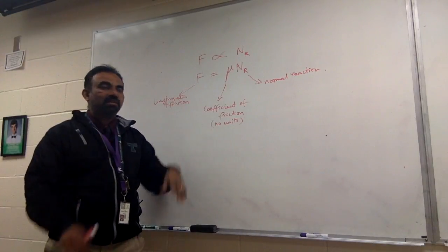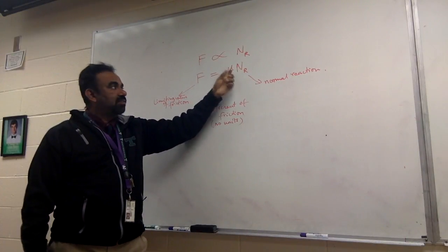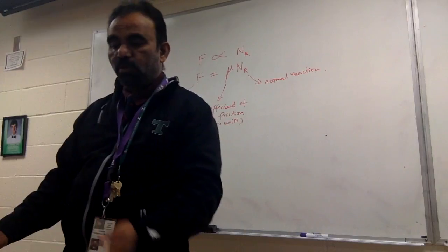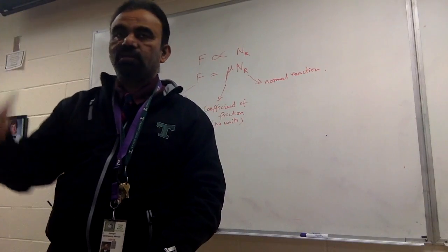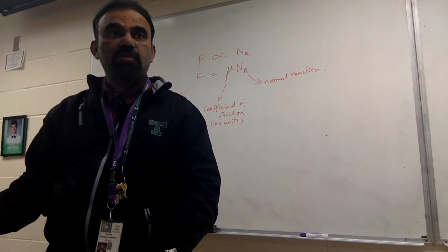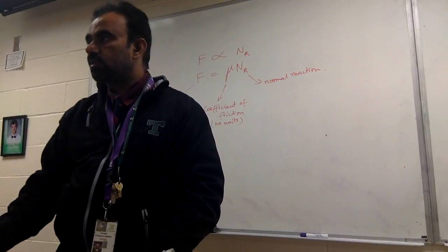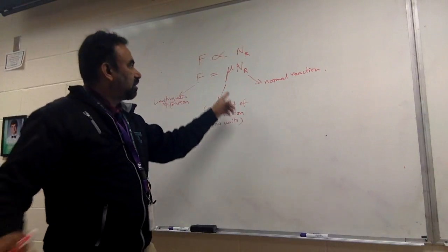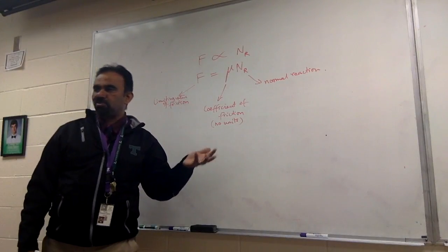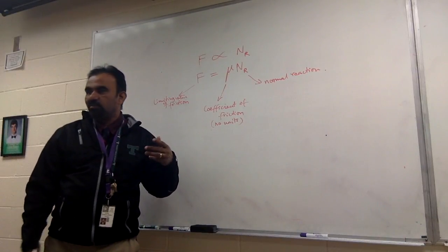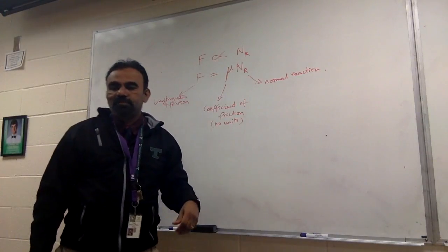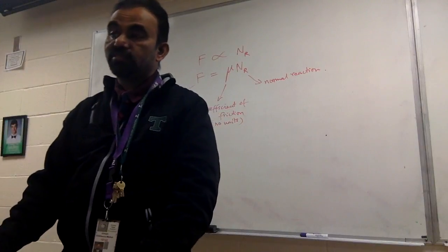The friction can be different. We're talking about solid friction. So this solid friction coefficient depends on the nature of the surfaces. Are we talking about book on the table? Or are we talking about rubber on rubber, or rubber tires on the road? Are you talking about wet roads or dry roads? Everything matters. So the coefficient of friction, normally it comes in decimals, like 0.5, 0.3, 0.2, 0.01 for snow. And this is the coefficient of friction that really comes in different for different surfaces.